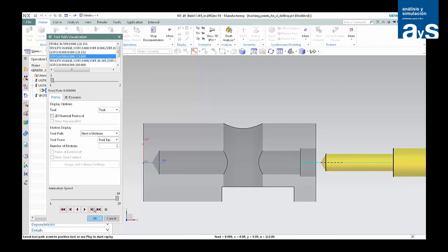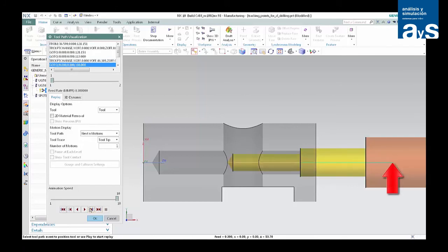Click Step once more, and notice how the tool path for drilling cycle is indicated by the tracking point at the top of the tool. Tracking point change indicates another change, this time from the top of the tool used for drilling cycle to the tip used for non-cutting.